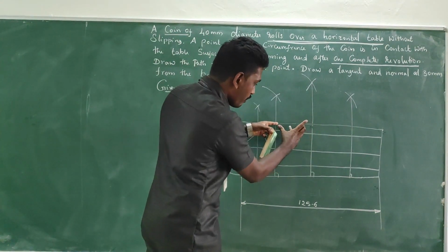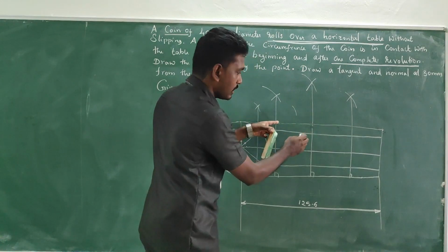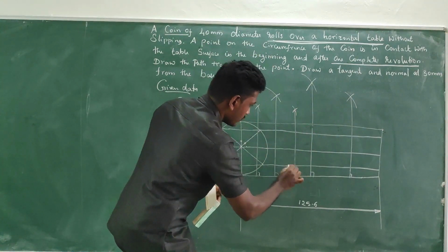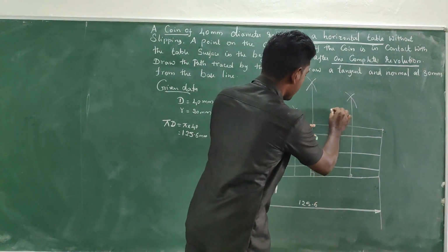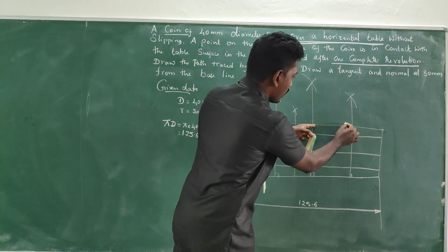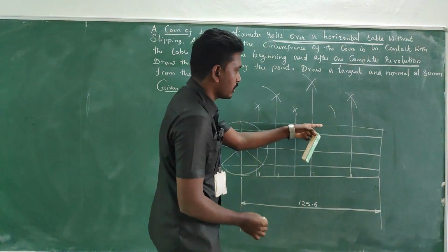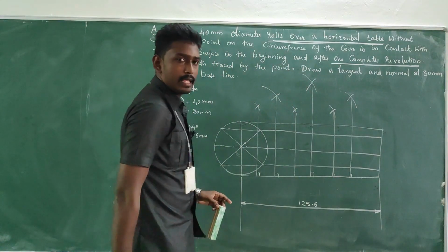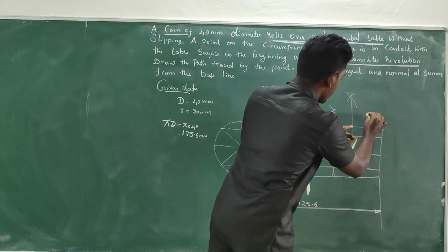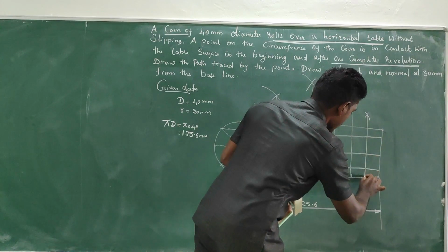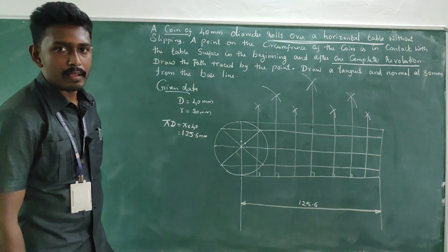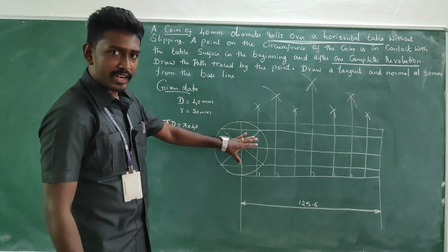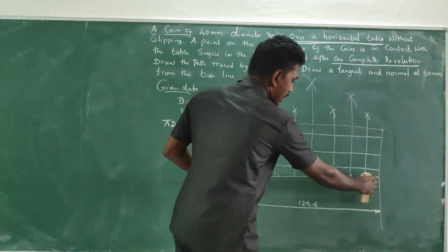So this is our segment. Take more than half of this segment and go for an arc. On the other end, go for an arc with the same measurement. You will get a line. In the same manner here, go for more than half, have a cut, and then just drop a line. You will get a line. In the same manner, do it here, so that you can divide it into 8 equal parts. So we are ready with the divided circle and divided platform.